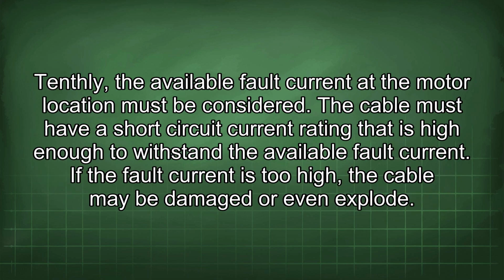Tenthly, the available fault current at the motor location must be considered. The cable must have a short circuit current rating that is high enough to withstand the available fault current. If the fault current is too high, the cable may be damaged or even explode.